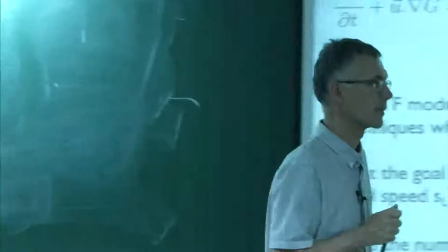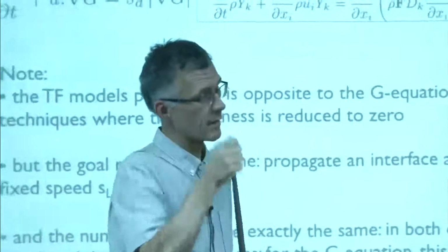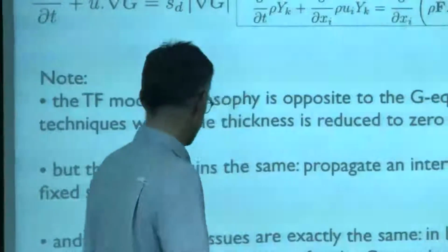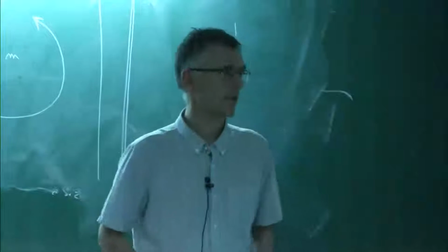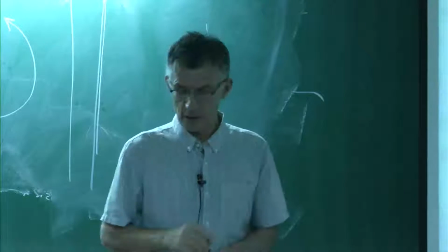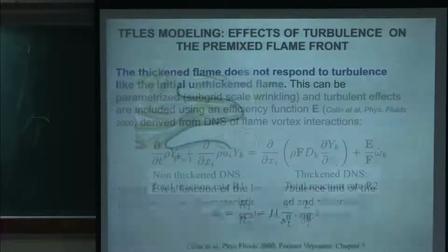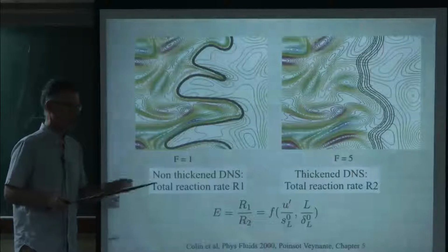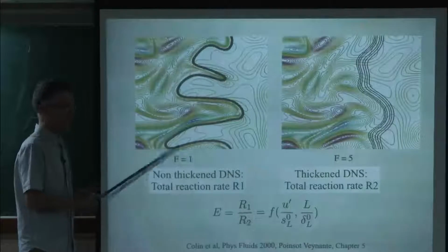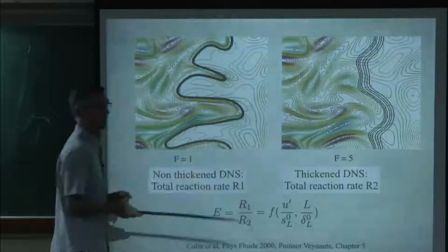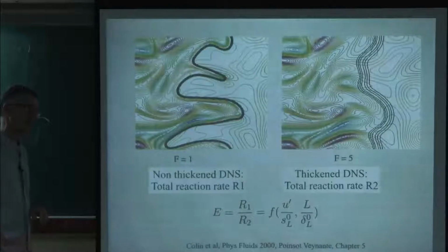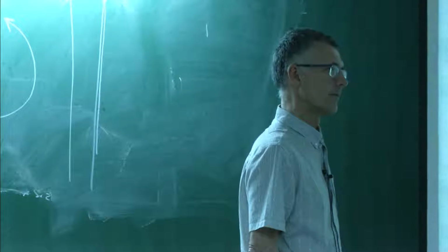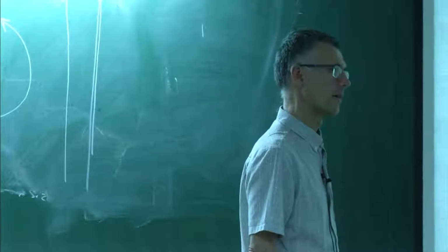I have a doubt in the second flame model, like there's a thickening factor when you give the number of grid points that are inside the flame. So if I vary the grid layer, suppose from 3-4 points to say 10 points, the results show some difference. So when I don't have the experimental data, how do I say which one is the right one? No, wait. Here, when we do the DNS, we do that only to build the efficiency function. Now, when you go into the code now, in an LES code, and you change the mesh, normally the results won't change. That takes that into account. Normally, there's no effect. That's only to do the DNS, that we have different results here and there. I did LES cases for two cases, same geometry, and I used different grid points, 3 and say 10. The results were not the same. That's what I'm asking. How do you decide how many grid points you have to use?